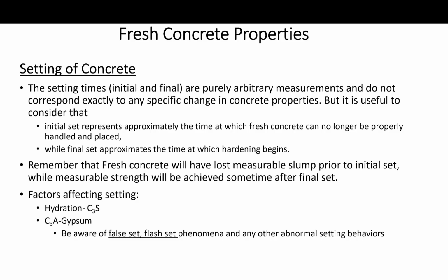All right. So setting is also accompanied by a decrease in electrical conductivity and an increase in the velocity of sound waves propagating through the paste. So the measurement of either of these properties could form the basis for an adequate test for setting.